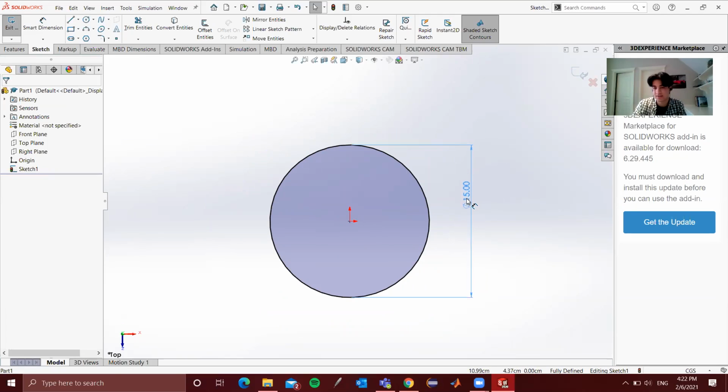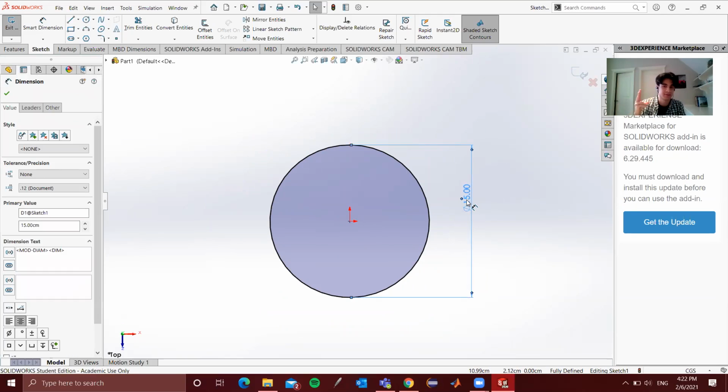That's precisely because we've limited two separate things here. This is sort of a general rule for CAD, but essentially whenever you're creating a sketch, if you want a sketch to be fully defined, it should not be able to move at all. And the other way is it needs to have its length defined in some way, or its physical properties defined in some way.